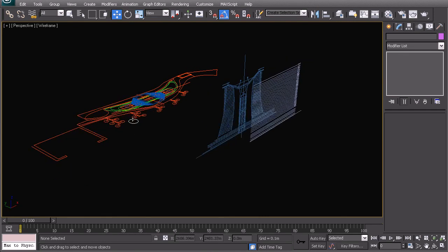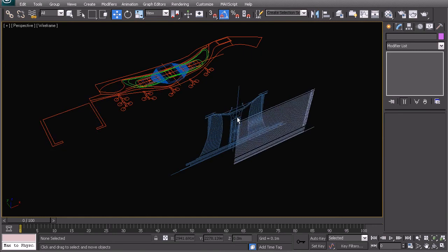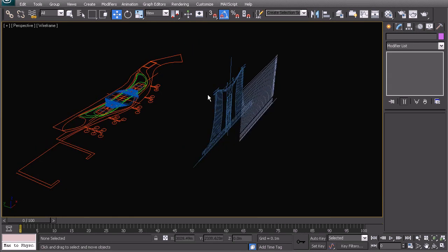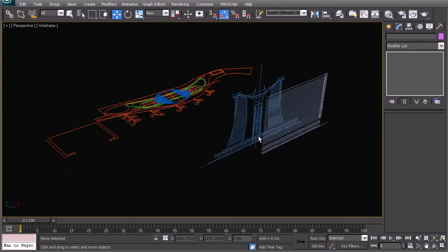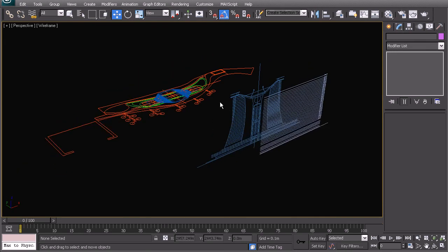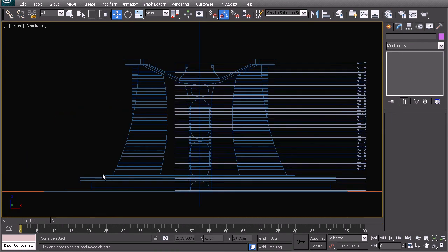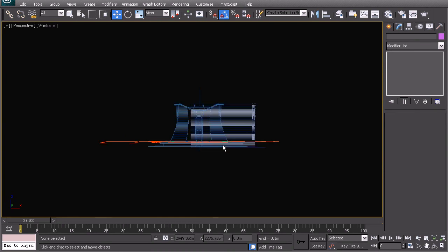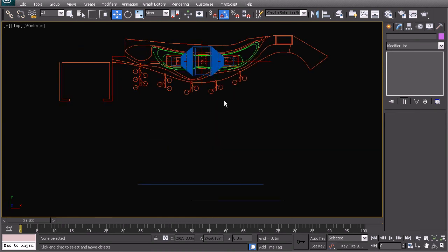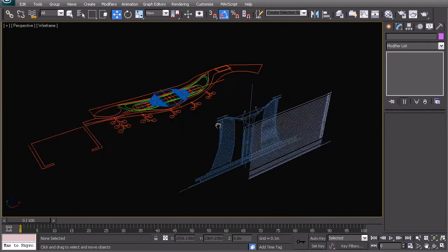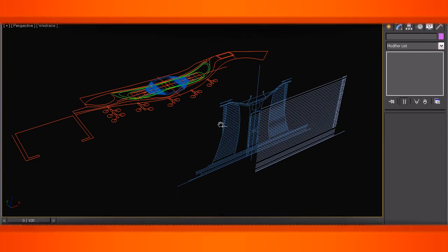What we've covered, just to recap, is we've imported our CAD plans and we've checked the position in the X and Y according to our existing model, and then we have rotated up the elevation and the grid lines to be correct in the right viewing plane, so that we can easily go into your front view and you can model in both front view and plan view. Great, so that is it for this video, and we will start modeling in the next one.